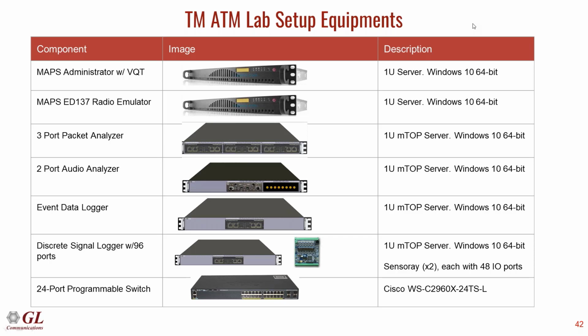They can be running up to 200, 300, 400, thousands of calls if it's necessary, and for long durations. Normally, what you would do is create a large amount of background traffic, PTT squelch sessions, and also simulate different types of messaging like main standby switching and so on. You create a script in our telephone emulator and our radio emulators. As we talked about earlier, you can predefine profiles that create certain message sequences, and those are repeatable. And you can create this kind of background traffic that is very much similar to the real world, in addition to regular traffic with actual voice traffic.